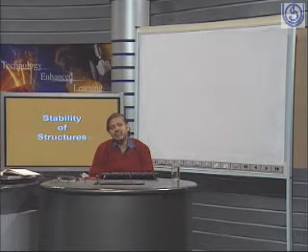So till now we have discussed that external stability is called when the body does not move as a rigid body in relation to any three mutually orthogonal axes, and the movement or the change in geometry of this structure is not appreciable as compared to its dimensions.